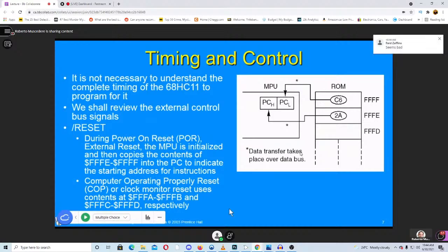How could that happen? Well, it's definitely bad, but why would that happen? You just took a photograph. How could it know there's a photograph? So what was happening? I'll give you a little bit more of the background. Well, there was a flash. The flash looks like just light, but there's different wavelengths of light. So these particular flashes were emitting a radiation where the power reset circuit was not properly protected by this radiation.